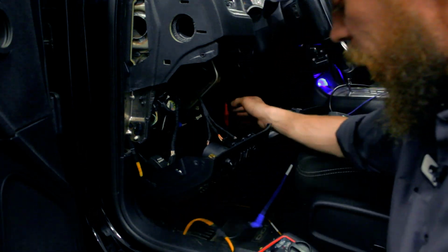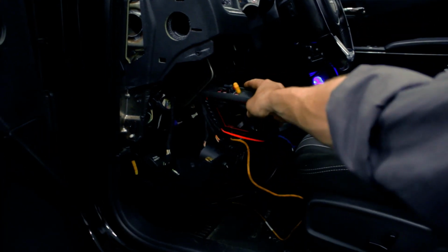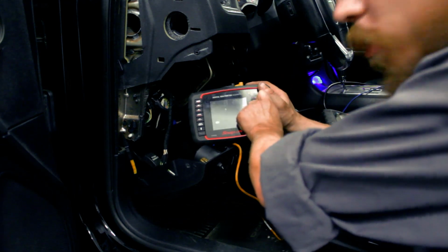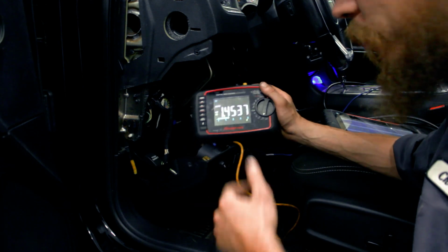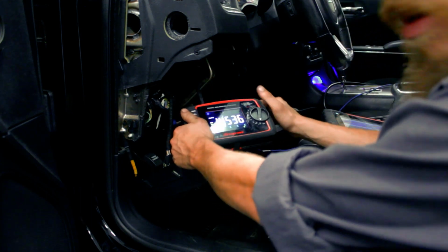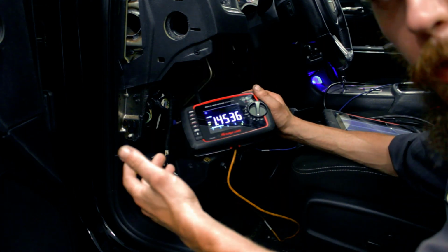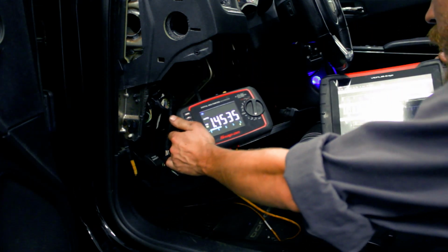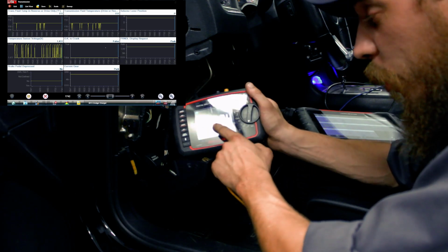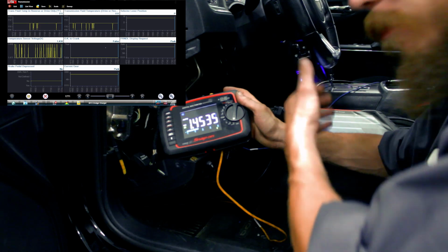And what we're hooked into here, and you'll see the voltage reading in a second, is just a regular old multimeter. You will see our voltage is inverted. So I've got my positive lead to ground, I've got my negative lead to my temperature sensor. There's a reason for that, which we'll get into in a second, but ignore the negative. We have 1.45 volts, which agrees with our scan data pretty closely of our 1.41 volts.